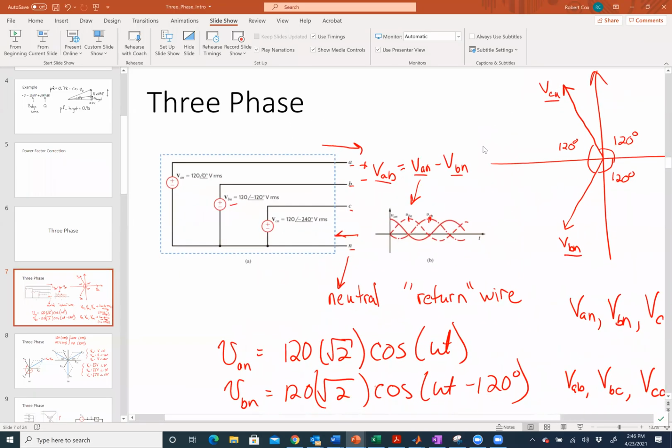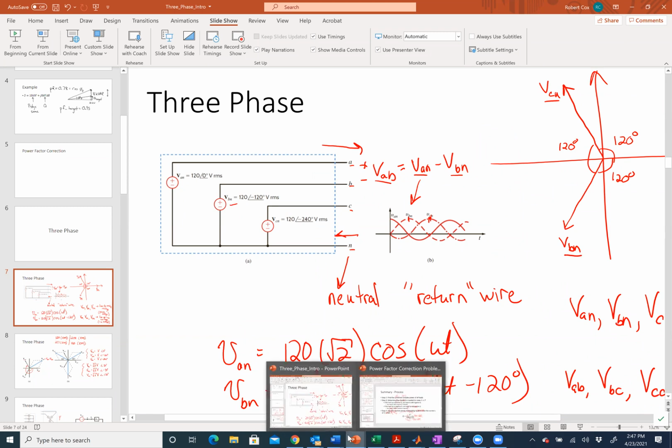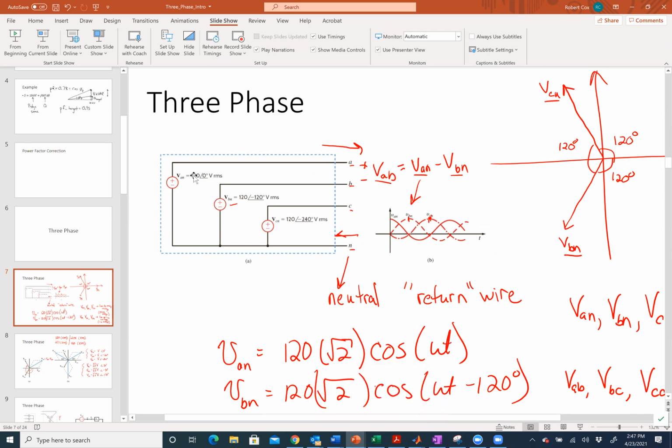All right. Tesla's big thing is if I take a motor, which is basically a round piece of iron, and I put windings 120 degrees apart from each other spatially. So one here, here, and here on a motor. You create what we call a three-phase motor. And we talked briefly about the benefits of that. I'll talk again about them briefly here.